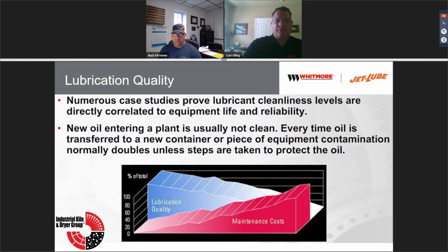And if you've got contaminated lubricants, you're already hurting yourself, as you're putting bad oil or dirty oil into a unit that you actually thought was clean oil. So you guys have the last say in the matter. So I really do like that kind of control. As far as at the plant level, you can request your distributor to bring in filtered oil and they're going to charge you extra for it, when you can actually do this yourself and control the cleanliness of the lubricants.